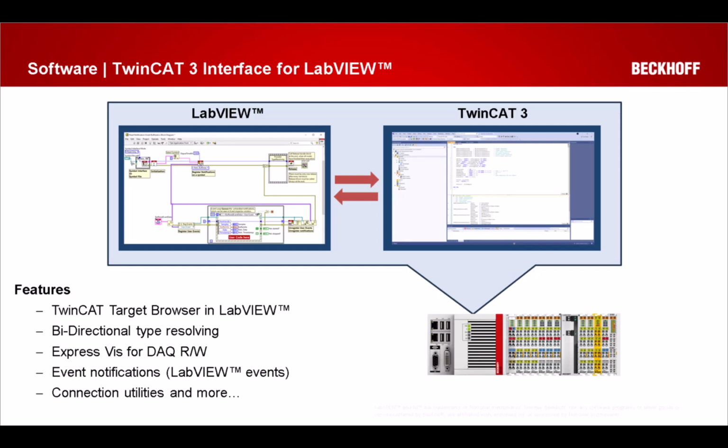There's a high potential for allowing it to be a means of control to further harness any of the functional extensions that exist in the Beckhoff platform, I'll say. Something worth noting here as well is with our Beckhoff IPCs, you are able to plant both a LabVIEW runtime or executable and TwinCAT on the same device without having to draw in an additional third-party PC or standalone PC.